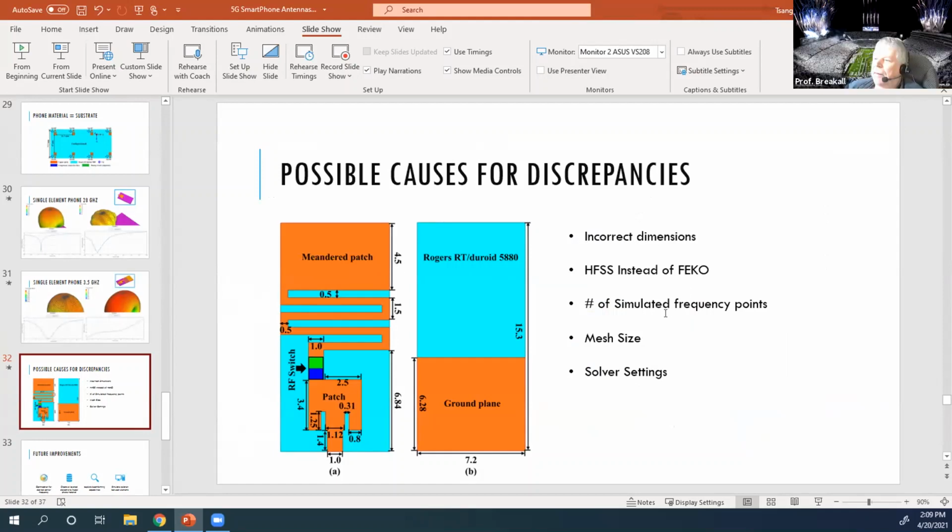I'm not sure. Well, there's a setting in the solver settings called MLFMM. That's the thing we talked about, where it looks to see if things are so far away that it just sets the interaction to 0. It might be that could have made it run a little faster, because you said it took long.